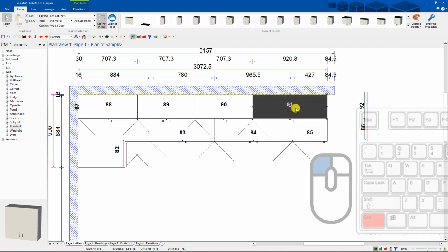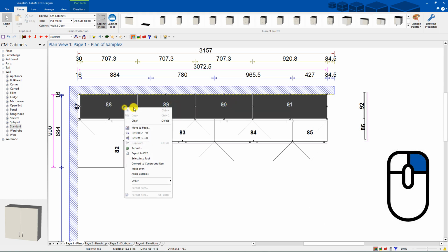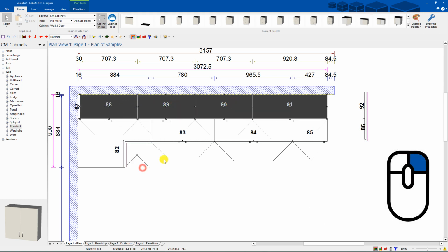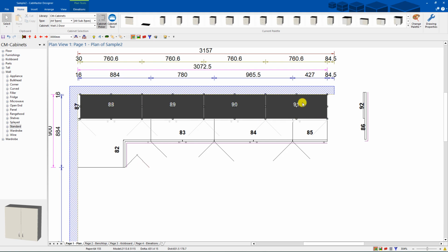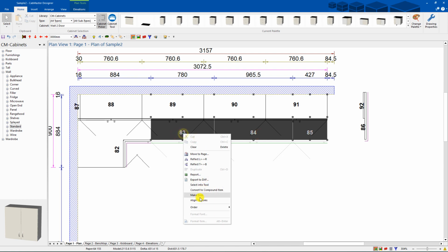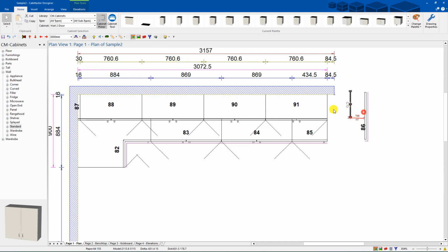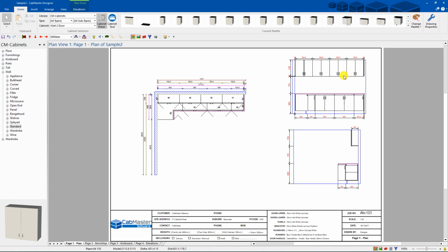So from there, I can click on that one, that one, that one, that one. Again, holding down Control. Make even. So I know it has to fit to this size here. At least now my doors are even sizes. Same again on these ones. Okay, make even. The cupboards remain to the same overall width. Then I can grab my panels and put my panels back on. And we know they will fit properly now. So you can see the elevations have updated.